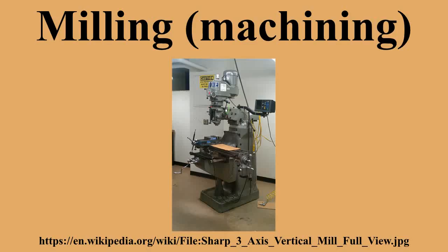Knee mill: a knee and column mill refers to any milling machine whose XY table rides up and down the column on a vertically adjustable knee. This includes Bridgeports. Planer-style mill: large mills built in the same configuration as planers except with a milling spindle instead of a planing head. This term is growing dated as planers themselves are largely a thing of the past.